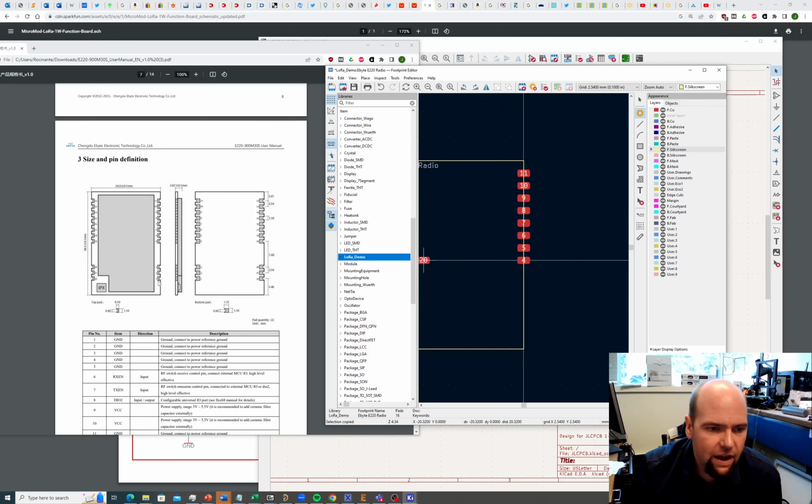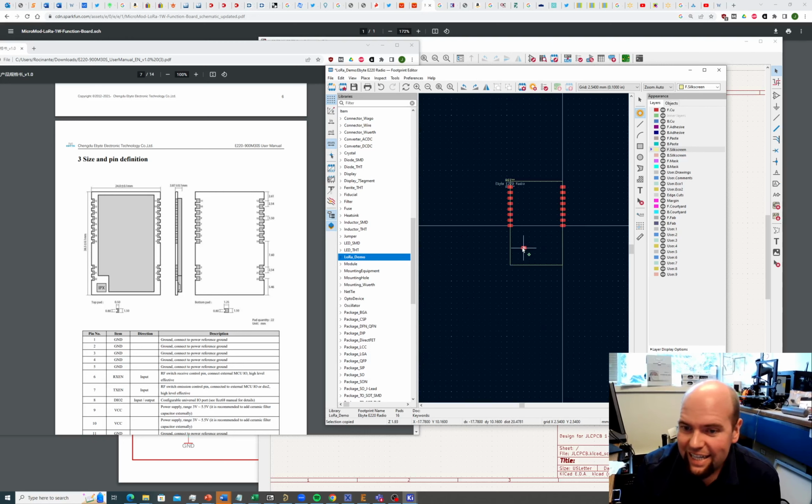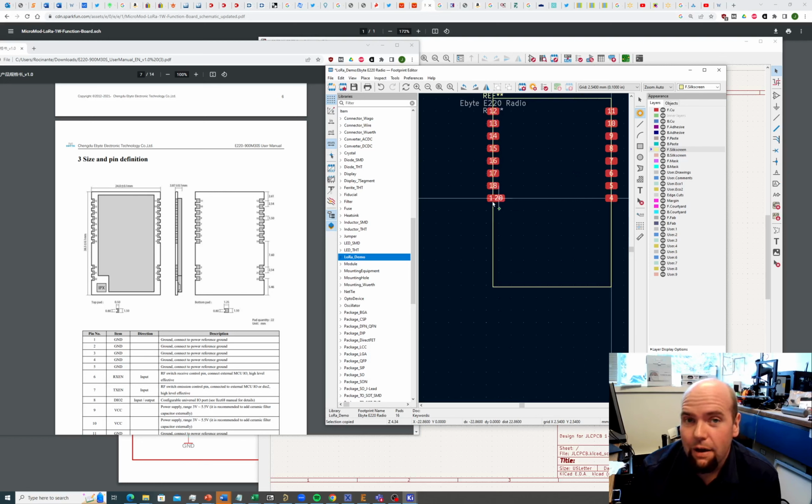Now we have to drop down to these other pins that are further down the board. So these next pins, technically they say they're 7.60. 7.6 millimeters is weird. My guess is it should actually be 7.62 millimeters, but it is what the datasheet said. If I had this physical chip, I would probably try to measure it with calipers, but even measuring it with calipers, your chances of getting 0.02 of a millimeter precision, I don't know. It's going to be close enough either way. 7.6, 7.62, it might be a little bit off.